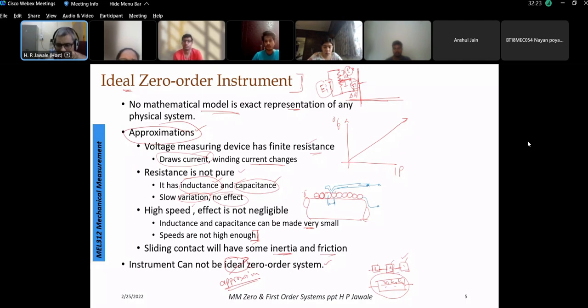And then in that condition, say for example my slider point is moving from point 1 to point 2, then possibly the distance it will consume, say whatever small distance xi that is applied here between the position of the slider from point 1 to point 2, there will not be a much effective change to the resistance, because at the mid position it will not show the exact amount of change in resistance between the length of the wire which is wound over the rod of diameter d between the 2 points.